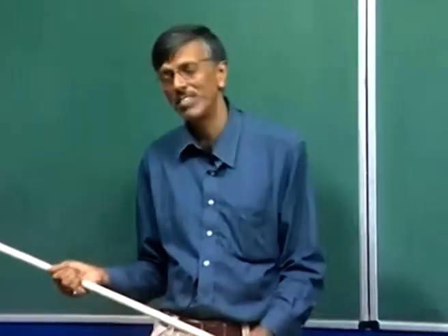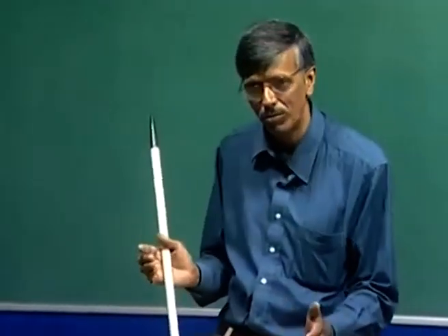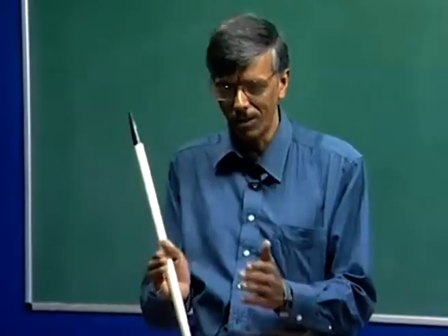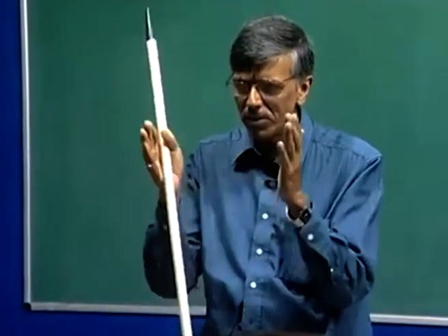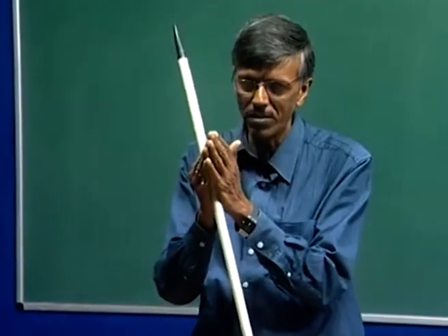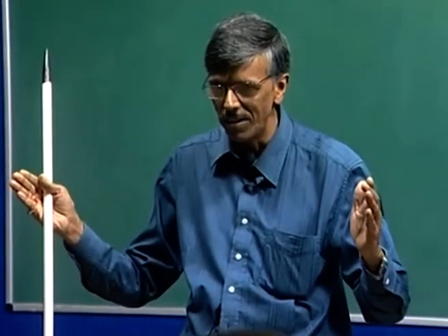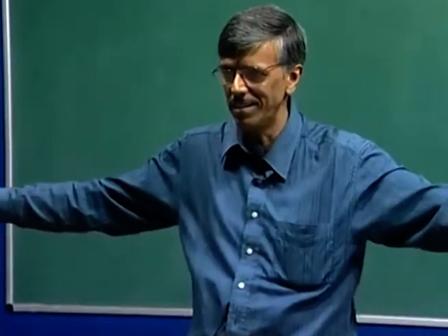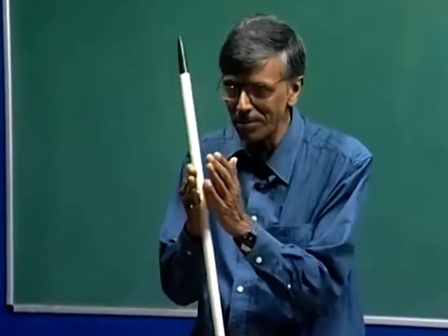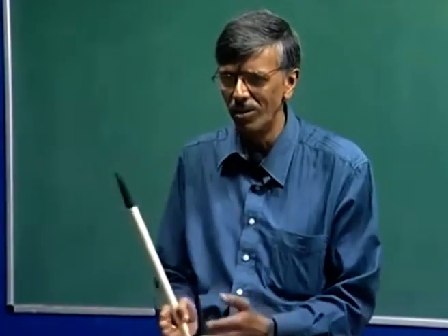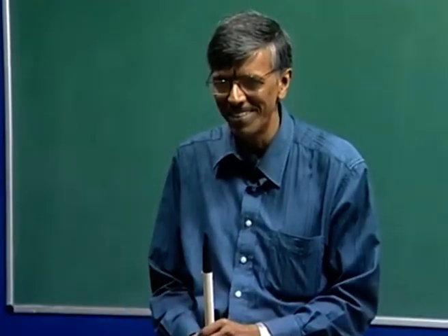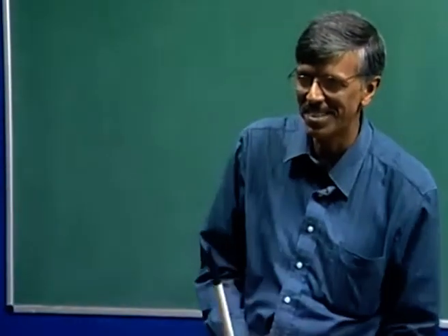This is true for all computations. That is why you may be seeing a very interesting aspect of flow computations: suppose I have a disturbance field which is localized. Now, if I compute that flow in a domain like this, I get one result. If I do it over this, I get another result. But my disturbance field is located in the middle. What is the problem? The problem is one of periodic extension.